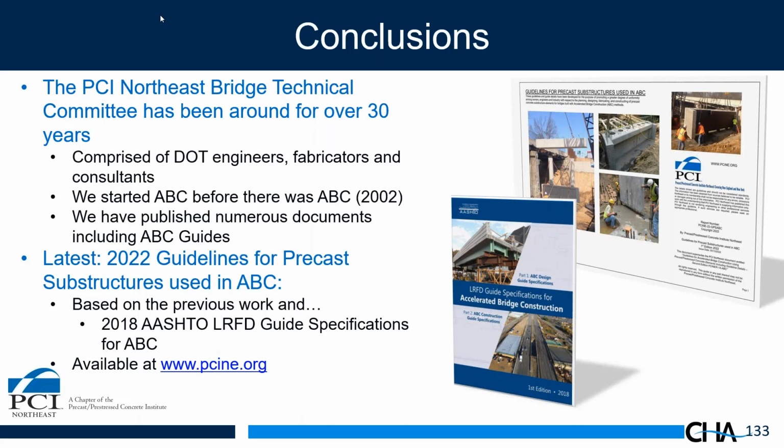So take the details I covered with wall panels, wall piers, or a wall abutment, a cantilever wall abutment, having dowels projecting out of the secant pile wall, and set a precast cap on top. There's no reason why that wouldn't work. I've never seen it done, but theoretically it would be easy to do.